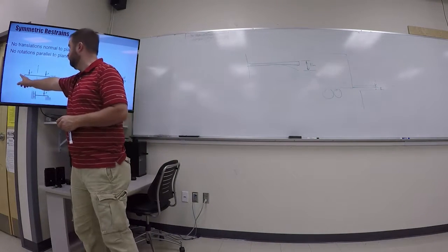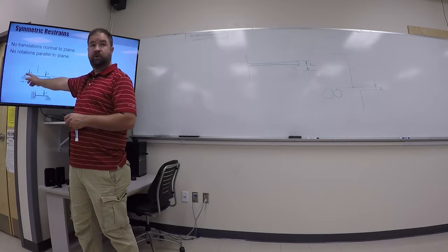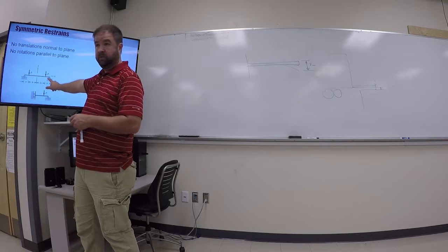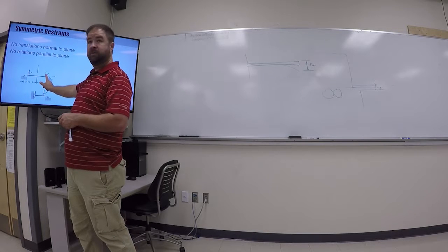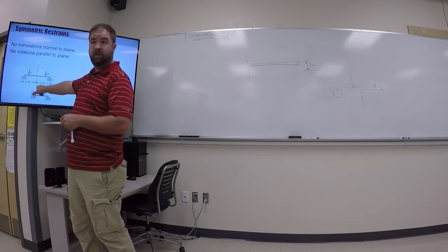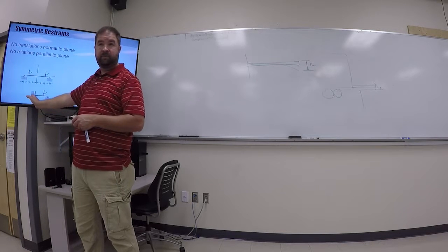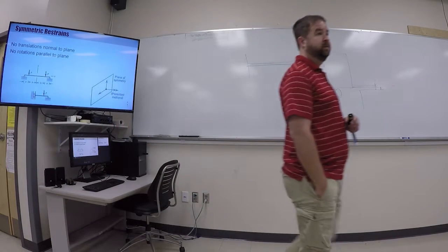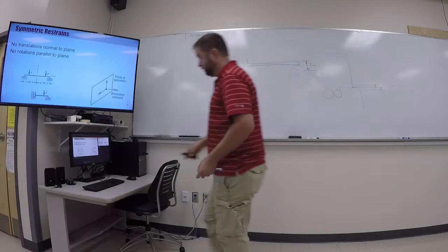So this is a simple little simply supported beam. We have a pin connection on one side, and this is showing a pin connection on the other side too, although in statics we typically make a roller on this side. We have symmetric loads. The loads are in the same direction on both sides. They are the same distance apart on both sides. And so I can simplify this problem by splitting it in half. And in doing so, I have to represent the constraints that are on that plane of symmetry. Okay? So let's look at that for a minute.